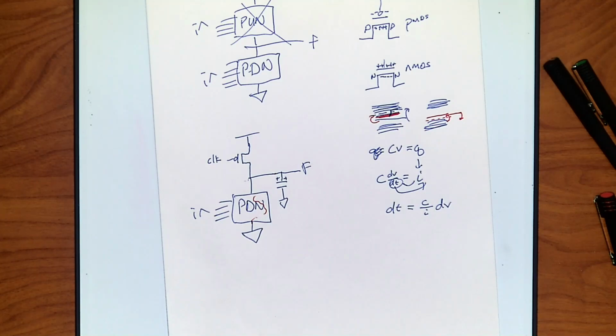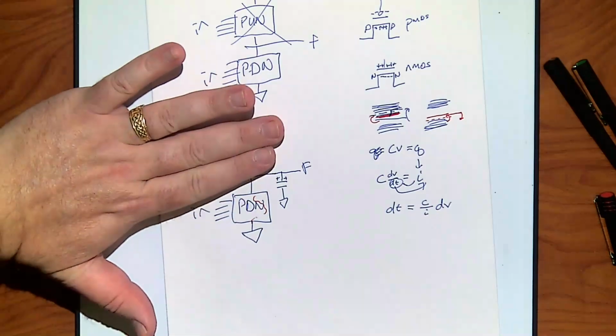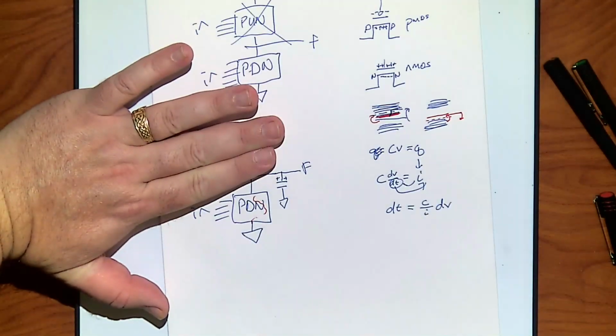Remember PMOS, I want a negative. So if clock is 1, I'm going to have a positive on that, which means unfortunately a negative on the other side, which means an N channel. I want an N channel. It's off. Okay, so, yeah. That circle tells you it wants it low to be on. So when clock is high, that gate is off, which means we just have our evaluate cycle.